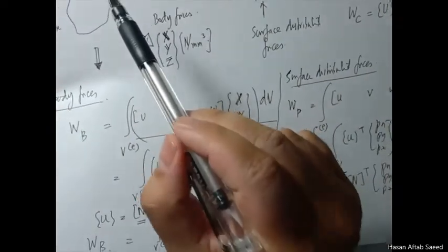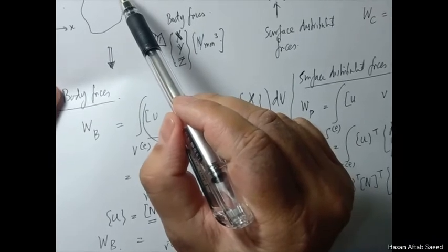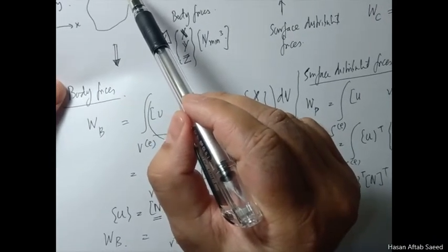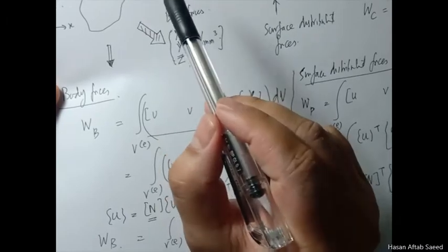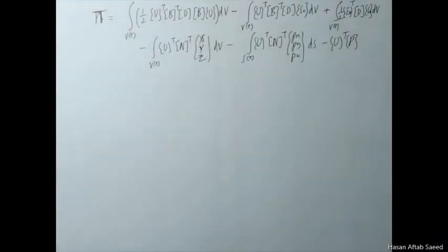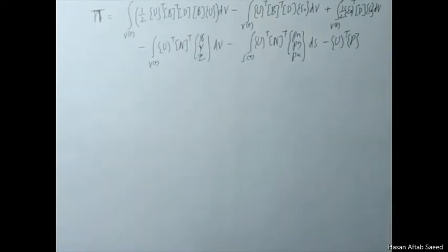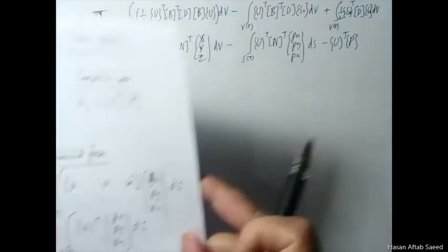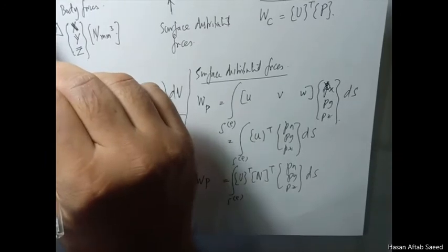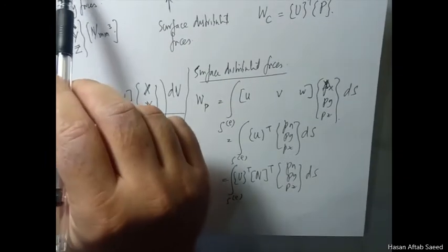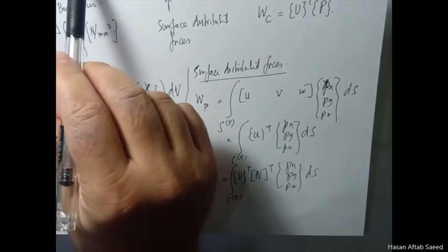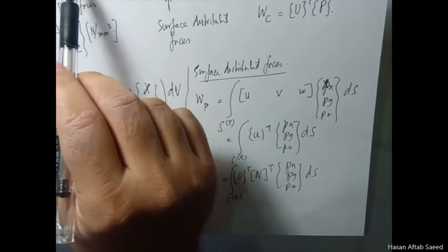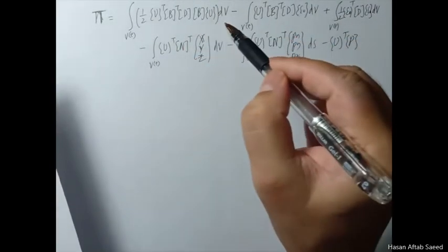It already applies on just one point, and you make sure in your modeling that at any point where there is a concentrated load, you place a node there. So that's not a problem. Now we have got this one. Now you have to realize that this is just for one finite element, and this E symbolizes that element. So this whole expression is just for one element.